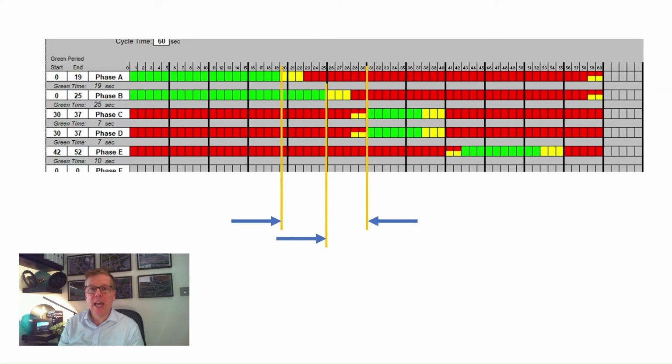The period between a stage ending and the next stage starting is called the interstage period. The interstage period starts when the first phase green aspect extinguishes in a stage and finishes when all the constituent phases start to display the green aspect in the subsequent stage. The duration of the interstage period will be governed by the individual intergreen timings for all constituent phases in the two stages. But in addition, phase delays are sometimes used, which if present, will also extend the interstage period.